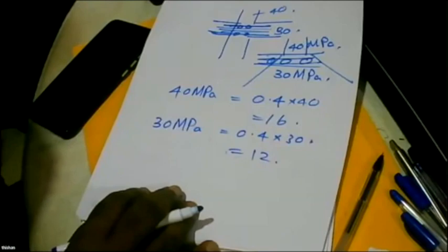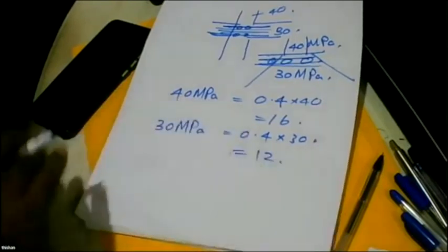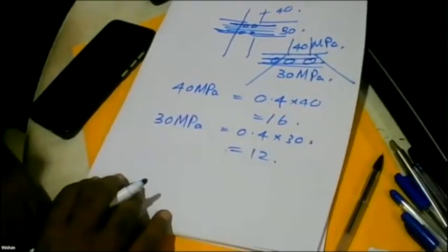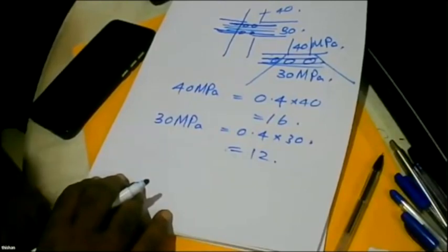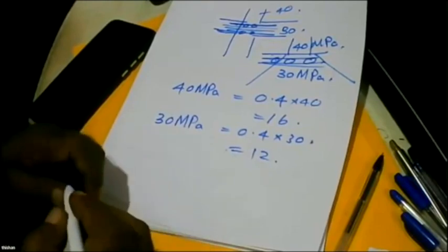So this difference of 4 can be easily accommodated by the reinforcement. So that's why the beams can be 30, columns can be 40. You don't have to do anything, but it is limited to 10. Otherwise, this difference will become too much for reinforcement to handle. So that's why the maximum difference allowed is 10. Is that clear? Have I answered the question?